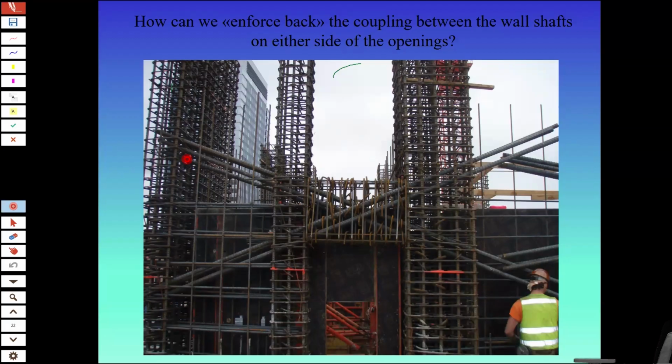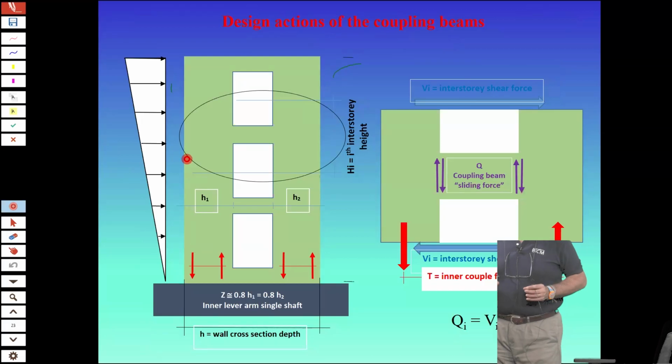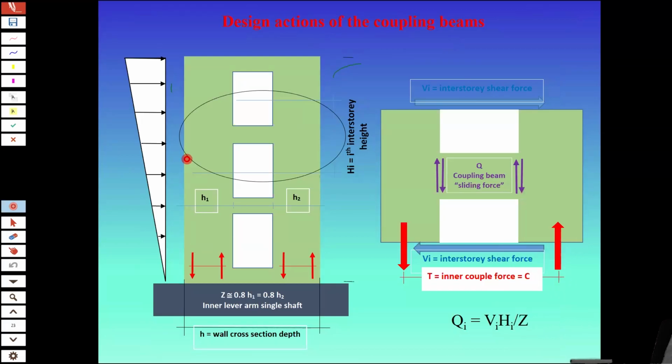They have just a minimum of longitudinal reinforcement in most cases, that can allow you to connect. You mount them, and then you complete the casting. But now let's develop a very simple case study example on how we design a coupling beam for this wall.